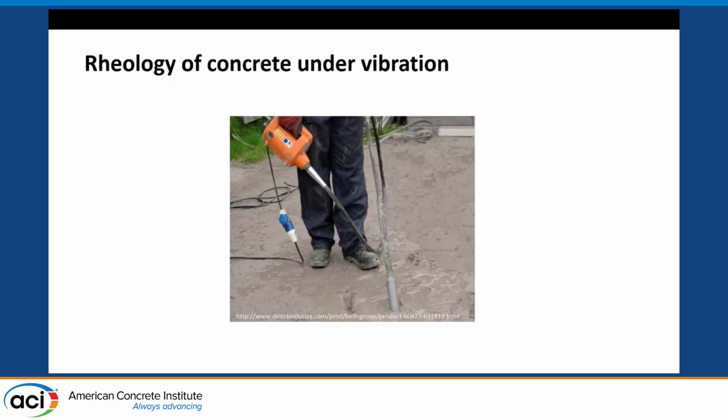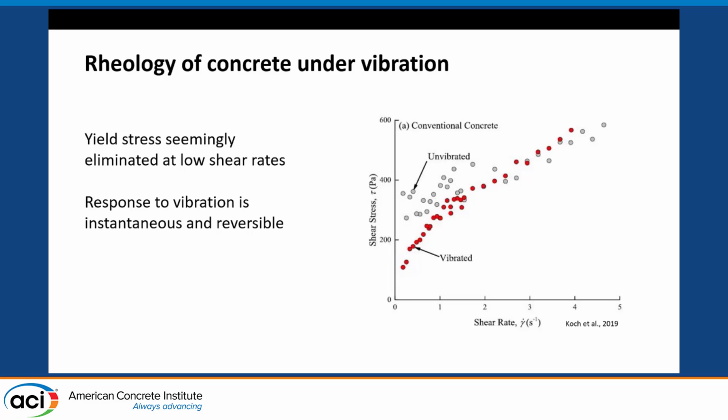Now, concrete thankfully has a dual rheological behavior. It can be a solid and a fluid simultaneously. And this is something we have been doing for a long time. We vibrate concrete. When you vibrate concrete, it can flow. You stop vibration, it stops moving. The yield stress is eliminated or seemingly eliminated at low shear rates, and response of concrete to vibration is instantaneous and reversible. This is a known feature of granular fluid.